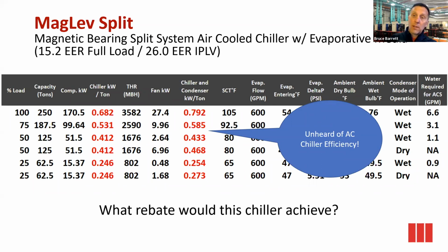When the day is favorable, when it's raining, you don't use any water. Only on those hot days when you're trying to drive down or force down your condensing temperatures. I found a lot of utilities offer rebates, both full load and part load. So if there are KCPL or something like that offering rebates, having a discussion about this could mean a lot of dollars.